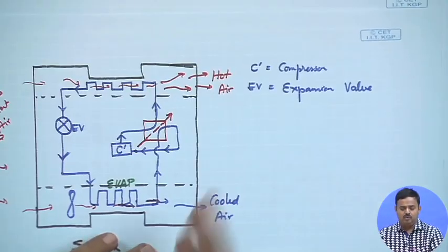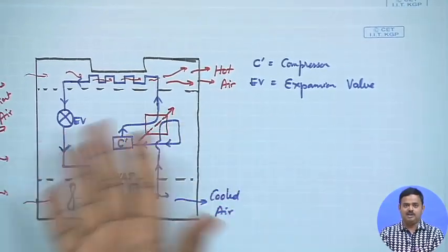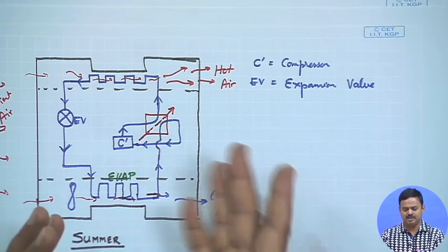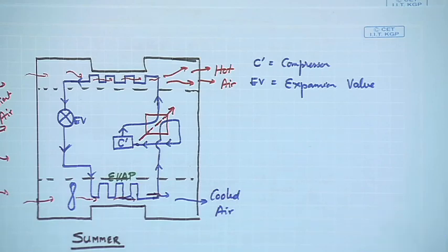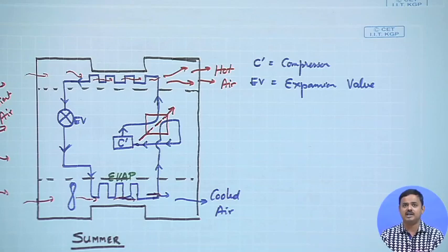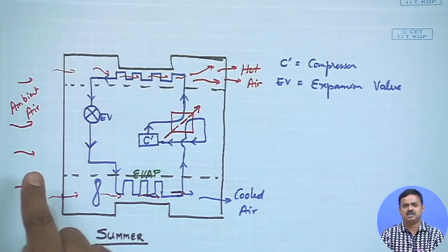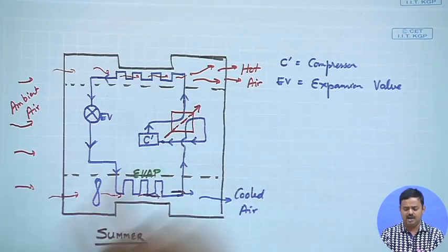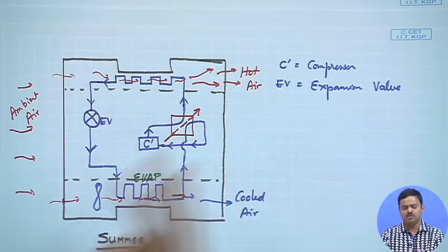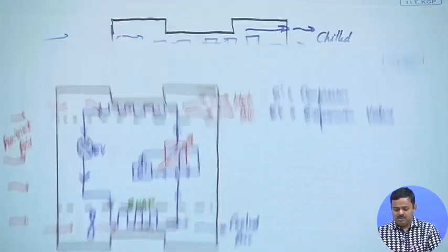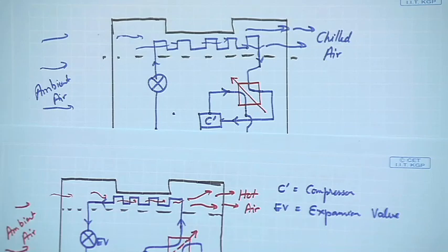And similarly, over here, when you get hot air in summer months, and if you are again talking about a small industrial enterprise, hot air has lots of applications. If nothing else, this hot air can be used for a vapor absorption refrigeration cycle, which you have studied. I have upgraded the heat energy from ambient, which was probably at around, let us say, Delhi summer will be 40-45 degrees centigrade. I can upgrade it to almost 70-80 degrees centigrade. Use this for something useful, for waste heat recovery. Clear?